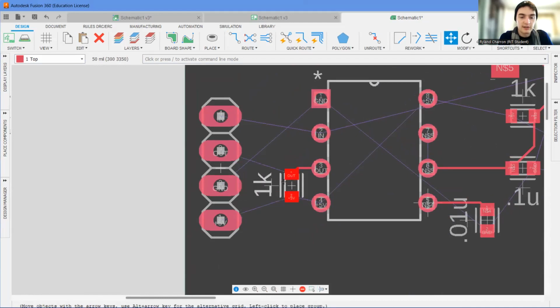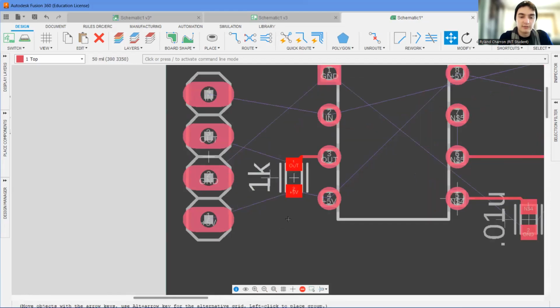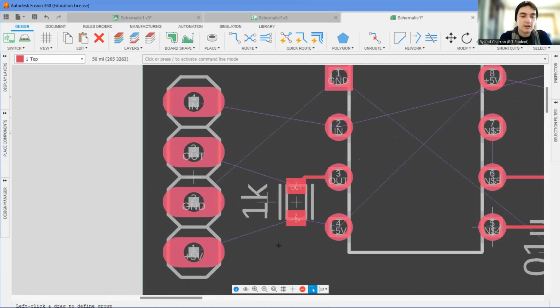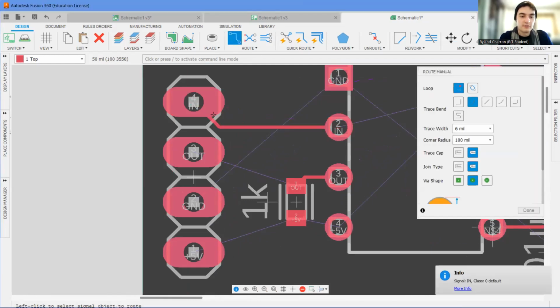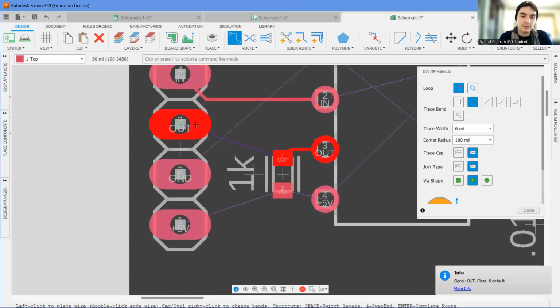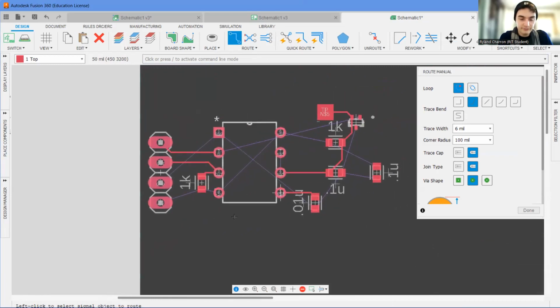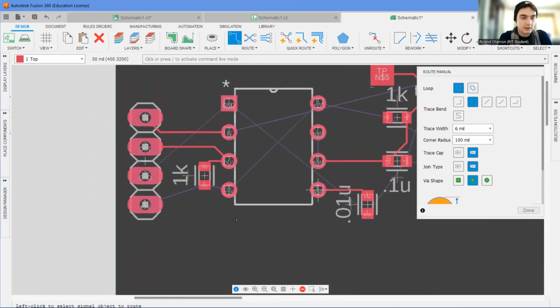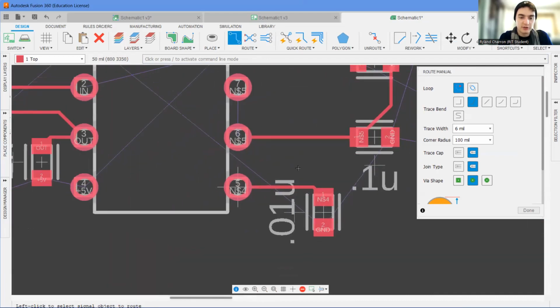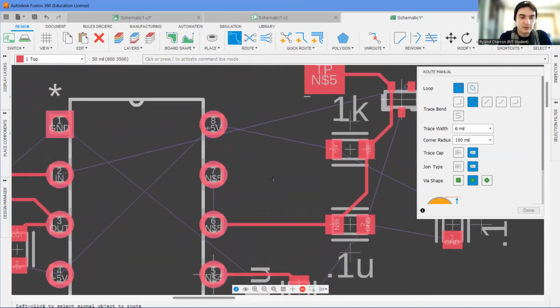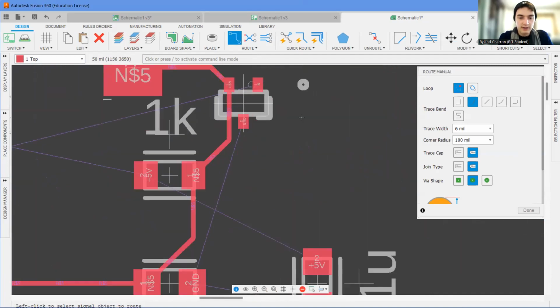So you can kind of see, by using location and really strategically moving things around, and trial and error, you can get a design that's much better. And this is what employers are looking for you to be able to do, and is not something that auto routing will teach you. Also, some auto routers don't even move components, so you have to place it correctly the first time, which never happens.